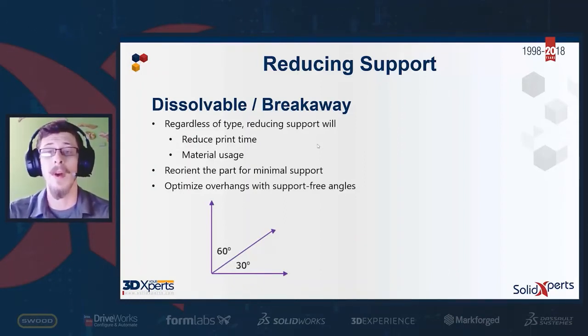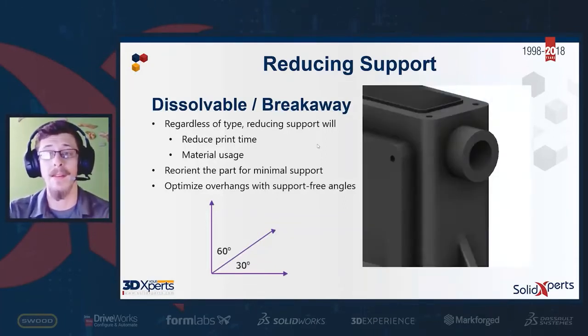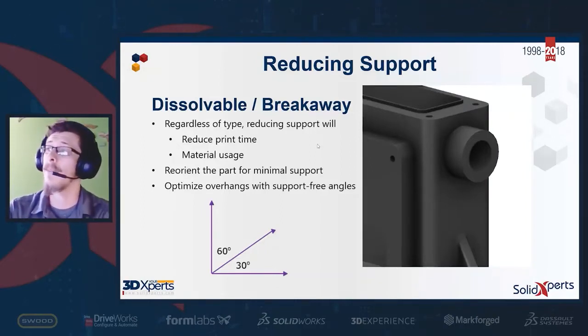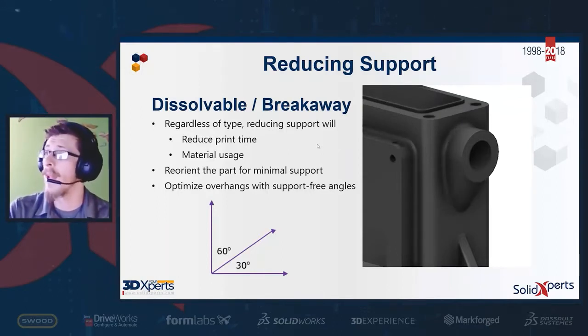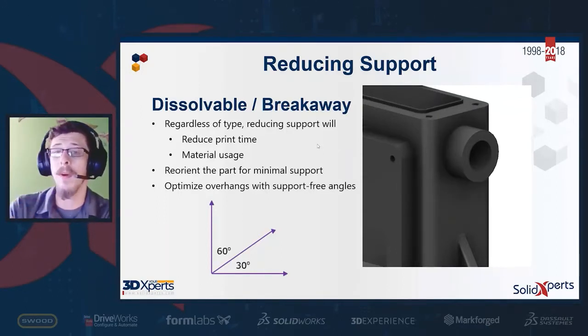That being said, though, with the overhang test, we've seen positive results at 60 to 65 degrees, meaning that we can print items at a 60-degree angle without any support. Okay. Now, for an example here, we have this overhang feature. I'm going to go ahead and click Next right here in the PowerPoint, and we can see here that what would normally have a certain amount of support underneath it that would then go down to the base plate or the build plate and then work its way up to the feature